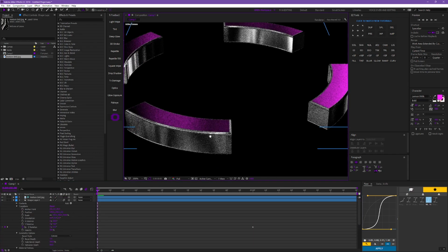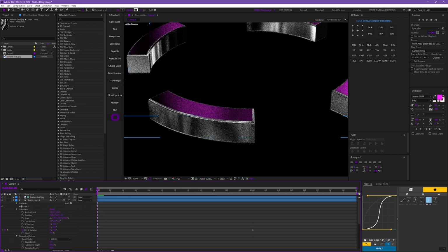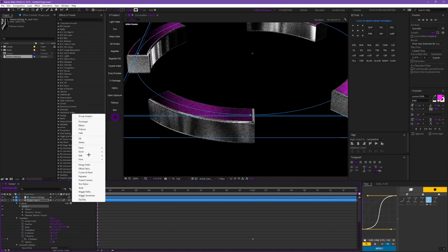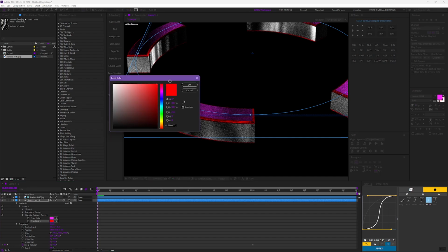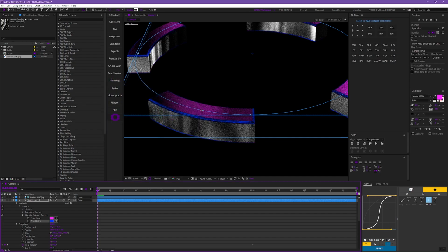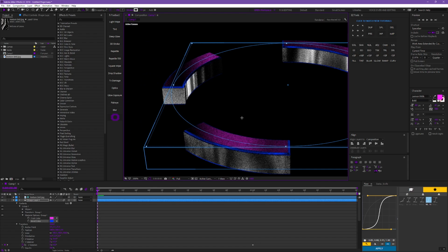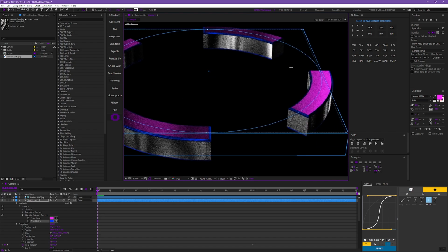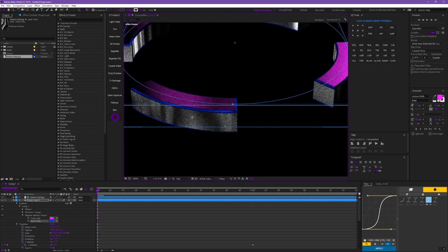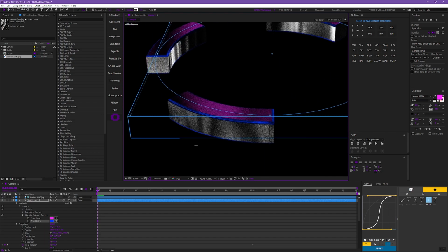What you can also do is, under the contents and the group, while you have group selected, click add. You can actually change the color of the sides or the bevel, not only the face, but you can also do the bevel color over here and change that to, let's say, white. Or actually, let's change that to blue or something like this, right? This is a pretty cool way of editing 3D text if you need to add a bunch of color to whatever you're making. I don't really ever use it in this way. I just like to leave it how I had it before, but if you need this option in any way, it is there for you.